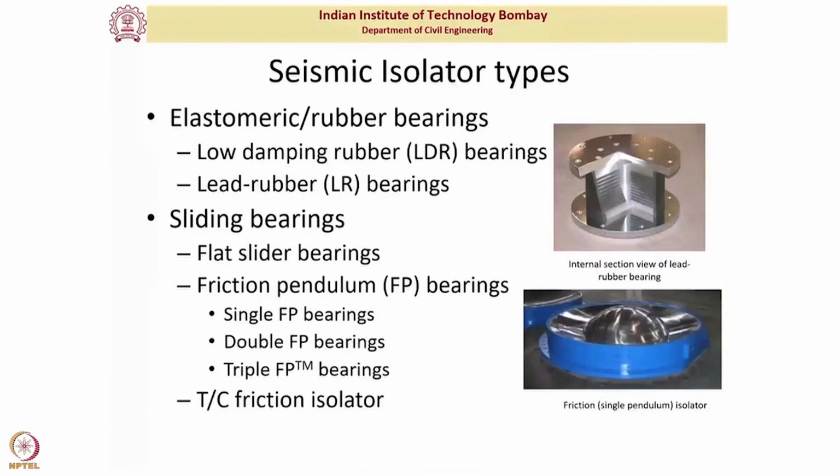Rocker bearings look something like this. You have a surface like this, and on this one you can have, let us say, a column, and here basically a slotted arrangement. Because of this rocker arrangement, it leads to a reduction in the horizontal stiffness. If you were a building designer, would you go for this type of bearing? Then why not go directly for sliding bearings? Okay, this would be much more stable. It would provide you enough capacity as well. And the force transfer would also be smaller.